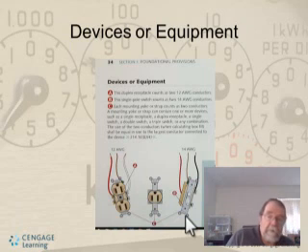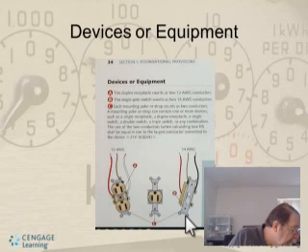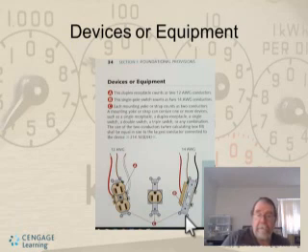Now there's a note here: a device or utilization equipment, if it's wider than a single 2-inch device box as described in Table 314.16(A), shall have double volume allowances provided for each gang required for mounting. What that means is basically if the box is used as a double box, if you mount them together, you can do that.